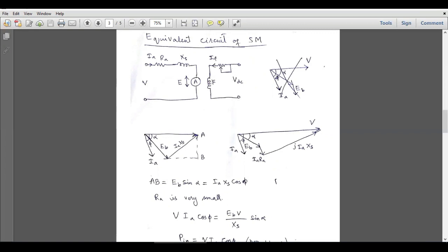This is the rotor side, and here we have the field winding. This is the DC voltage applied at the rotor, and here we have a current limiting variable resistor. So if we want to increase the excitation, we will reduce this resistance and vice versa.